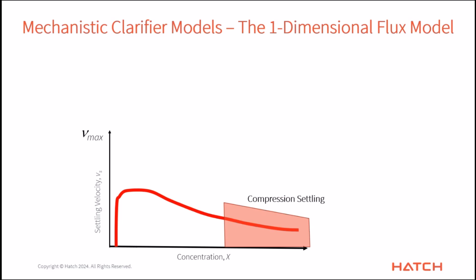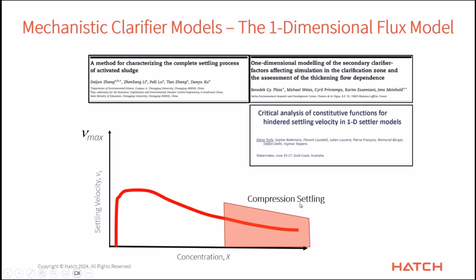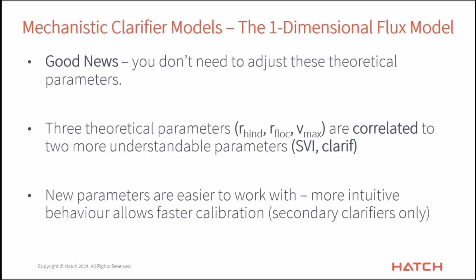Sorry, I forgot to discuss compression settling. We have a whole other model down here at the end that we added a couple releases ago for compression settling. When you get into very high concentrations, we have some other parameters here that will allow you to have better prediction of the thickening at very high concentrations.